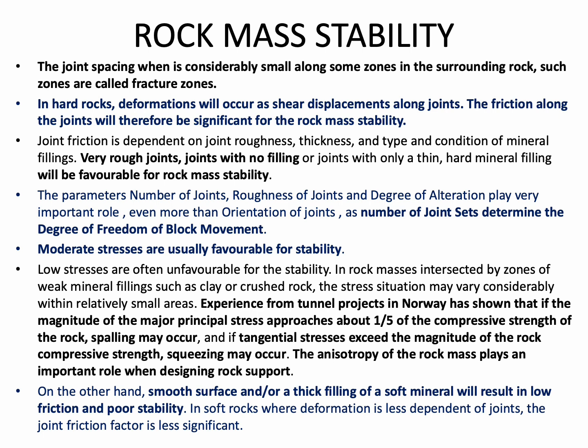The parameters, number of joints, roughness of joints, and degree of alteration, play a very important role, even more than the orientation of joints, as the number of joint sets determines the degrees of freedom of movement of various blocks.